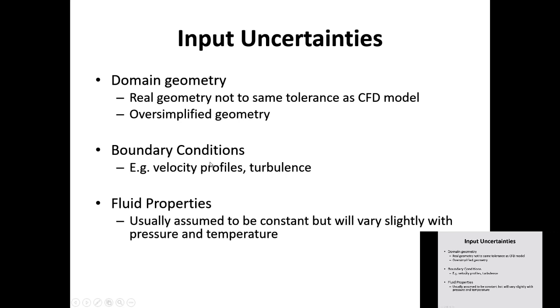And your boundary conditions could be wrong. So for example, for your pipe case, you had a flat U velocity profile coming in. It's okay for the time being for your case, but the actual velocity profile, can you get a velocity profile like that? You can't. It has a slight profile. At least at the walls, your profile is different.